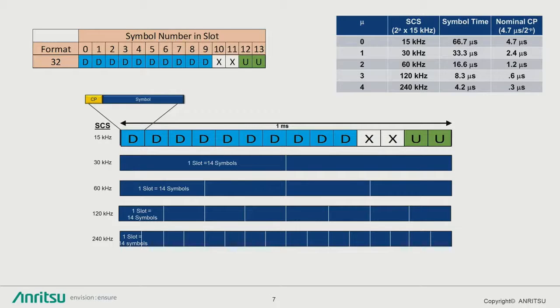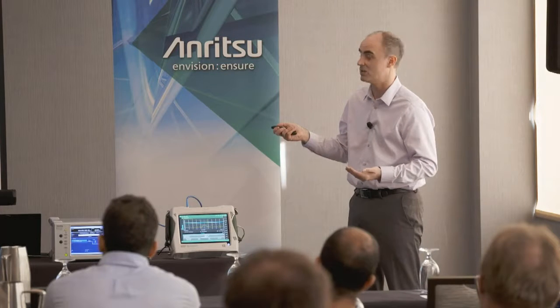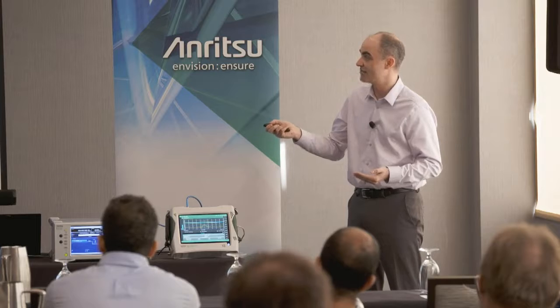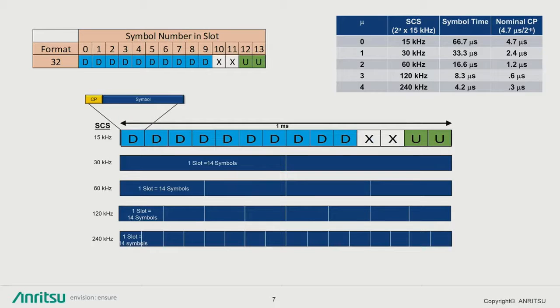So we're always talking about, well, if the frame is 1 millisecond and I need to respond in 50 microseconds or whatever, how do I do that? Well, you're not relying on every single frame. You're looking at the symbols within that frame because it's time-based, okay? Totally different than FDD. So try to reinforce that because as we go through this, we're going to build. So if there are questions, the hands need to go up now so we can iron those out.